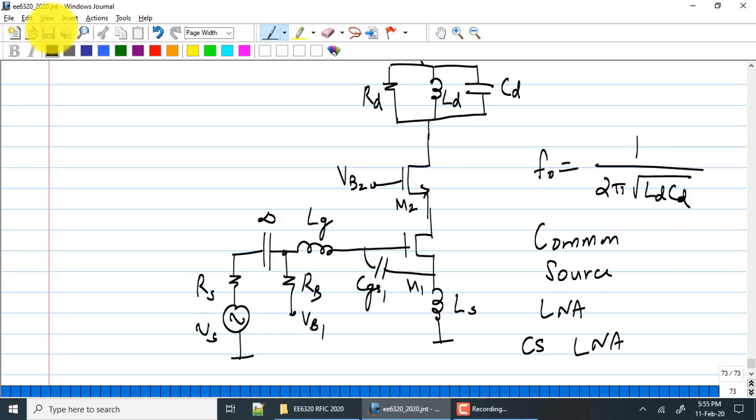What we'll do, we will do the basic analysis of the gain and noise figure. Then we'll try doing these two things that you suggested: adding capacitance in parallel with CGS, and adding capacitance in series, changing that infinite capacitance to some much smaller capacitance, some physical capacitance. We'll also see what that is.